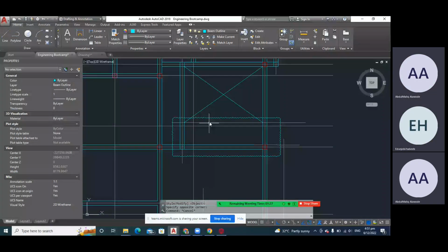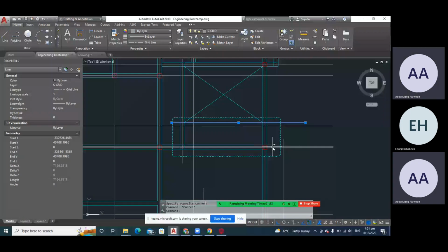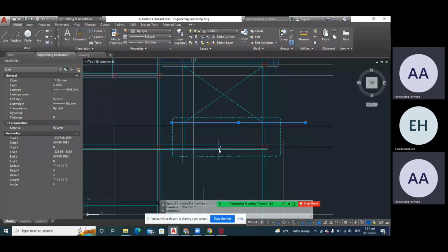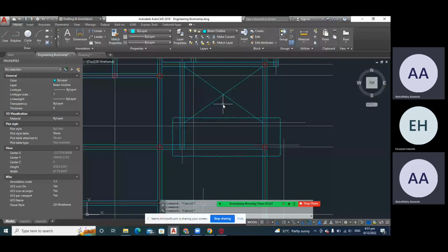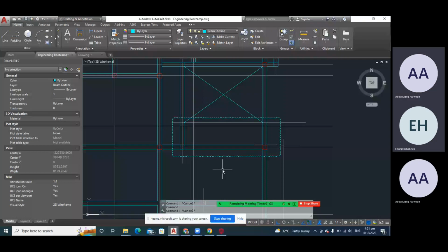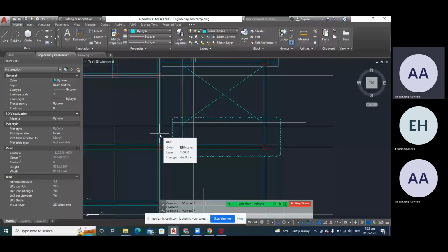Okay, this is the area. This is the slab I'm talking about. This slab looks like a cantilever, and if I'm the designer, I can design it to make it a cantilever. It depends on how I'm stripping it. If I'm stripping it in the YY direction first, that means I'm taking it as a cantilever. If I'm stripping it the other way, that means I'm taking it as a one-way slab. So that's where the slab strip comes in.